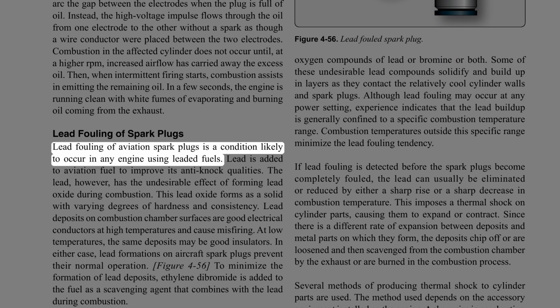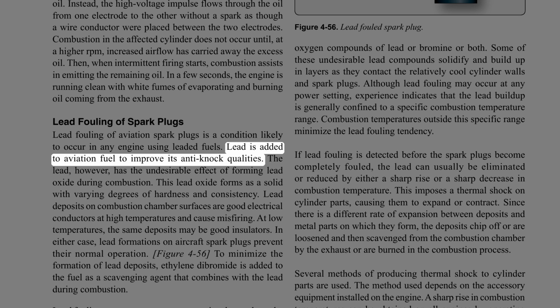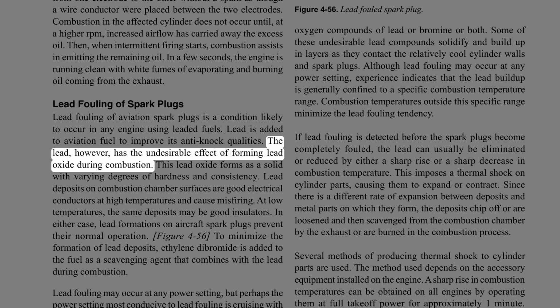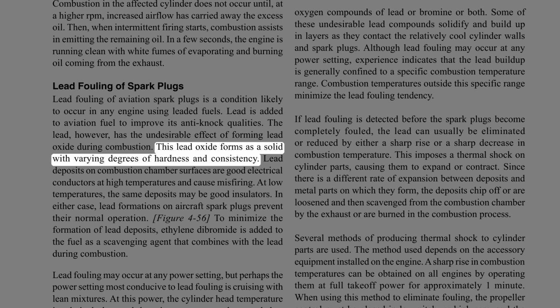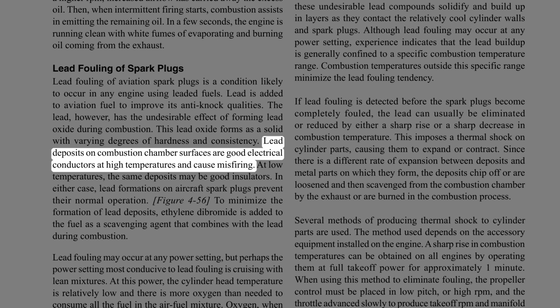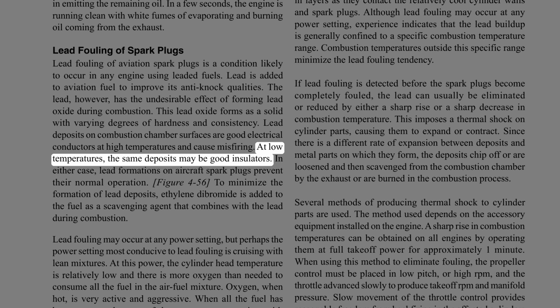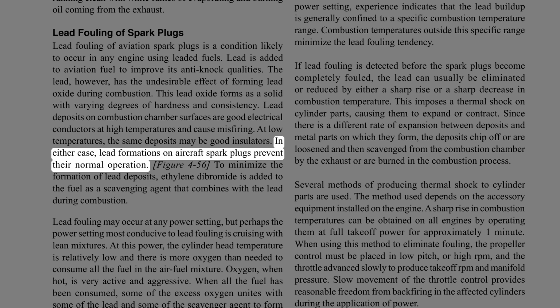Lead fouling of aviation spark plugs is a condition likely to occur in any engine using leaded fuels. Lead is added to aviation fuel to improve its anti-knock qualities. The lead, however, has the undesirable effect of forming lead oxide during combustion. This lead oxide forms as a solid with varying degrees of hardness and consistency. Lead deposits on combustion chamber surfaces are good electrical conductors at high temperatures and cause misfiring. At low temperatures, the same deposits may be good insulators. In either case, lead formations on aircraft spark plugs prevent their normal operation.